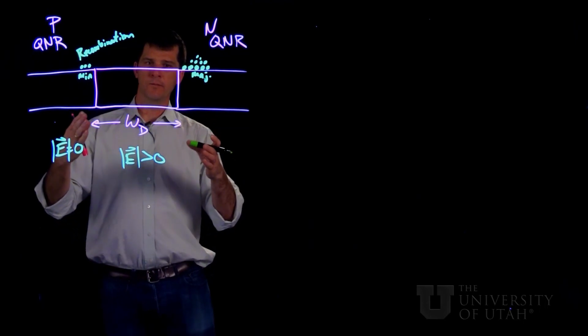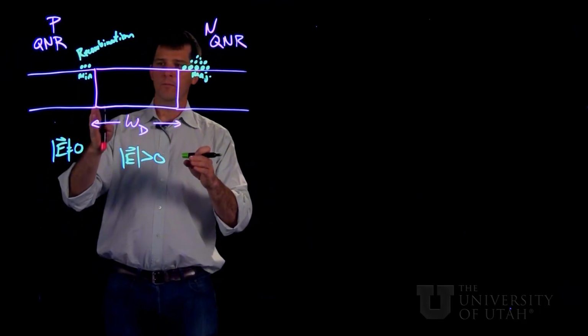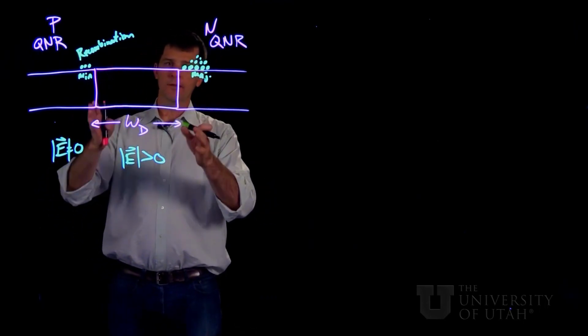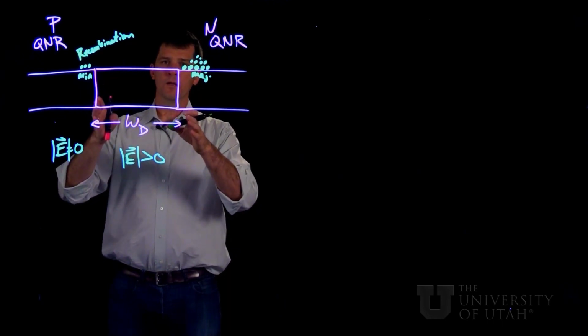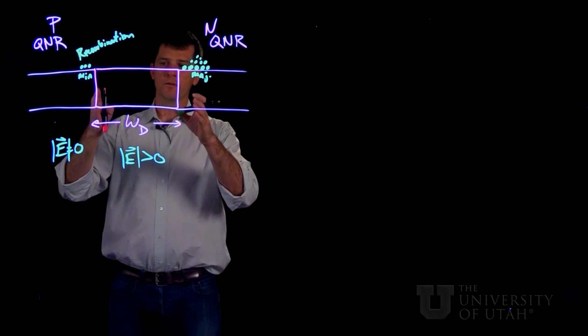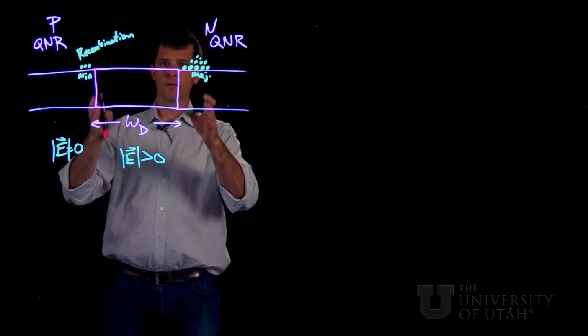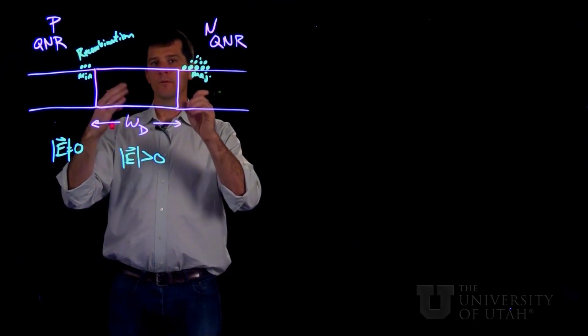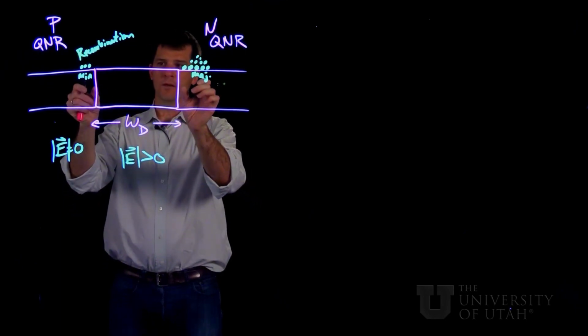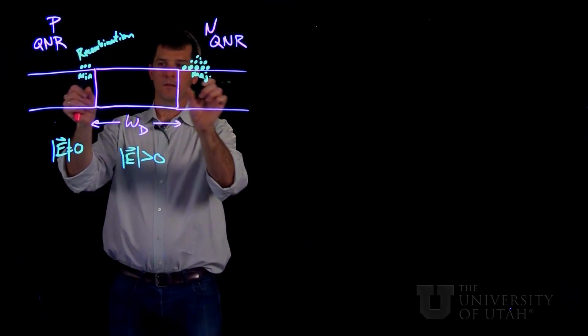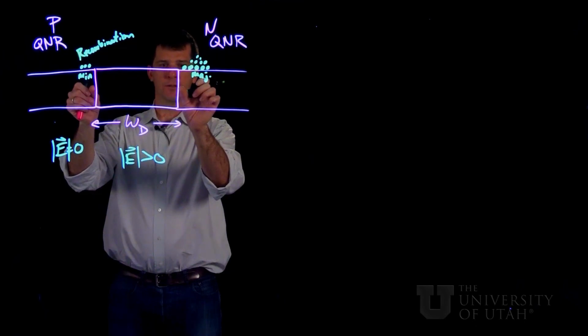So our strategy is going to be to try to find the boundary conditions for our ambipolar transport equation for minority carriers, with those boundary conditions being voltage dependent, and then solve for the currents that flow in these little regions just outside of the depletion width.